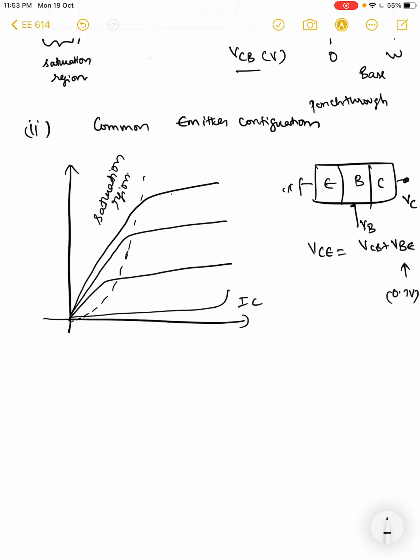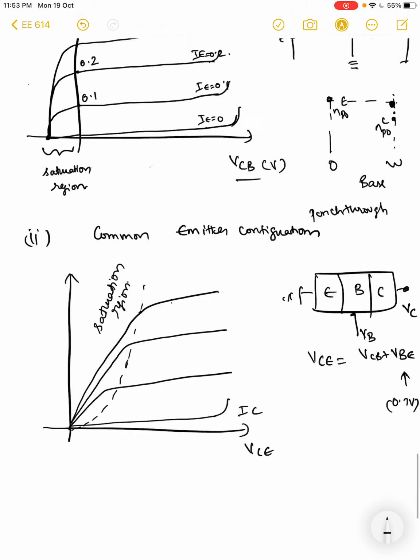because you can see that as you fall into the saturation region, the current starts to drop radically deep into saturation, right? As you start reducing the collector potential or increasing the base potential with respect to the collector potential, either way it's the same thing, right? As you start increasing the forward bias in the base collector junction, you will have the current fall down drastically. That is similar to what we saw in the common base configuration as well.